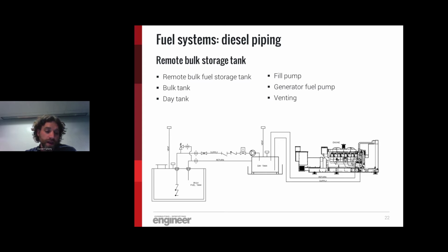And when considering how much suction lift is on a pump, note that because diesel fuel's specific gravity is less than water, the pump can't pull the diesel fuel up in suction as far as it can water, and it's limited to about 15 inches of mercury. If doing a system with large suction lifts, consult the pump vendor to determine whether you need a single stage pump or a two stage pump.